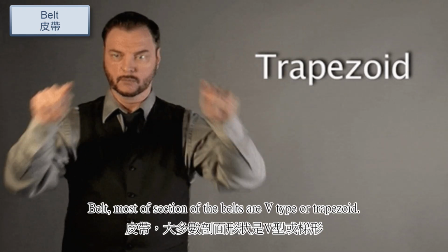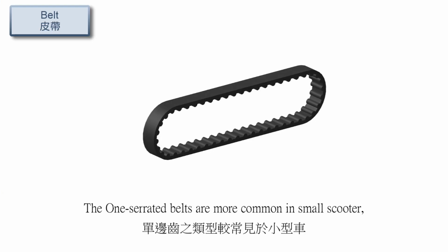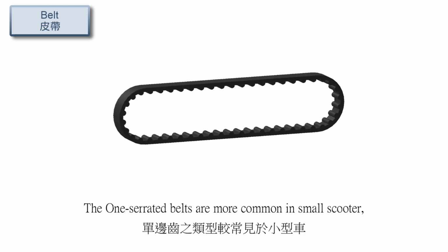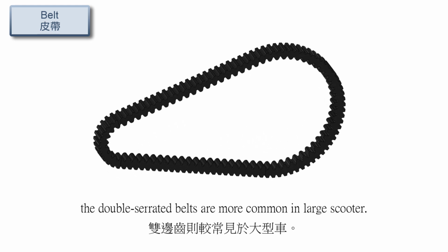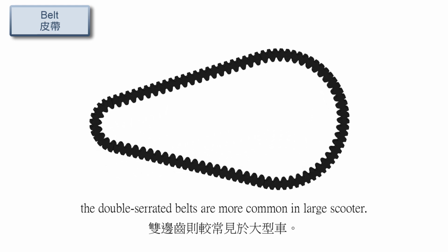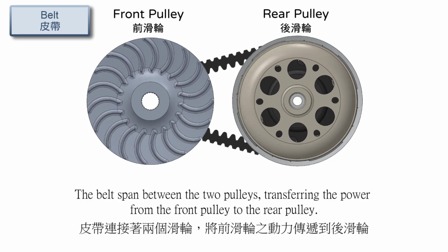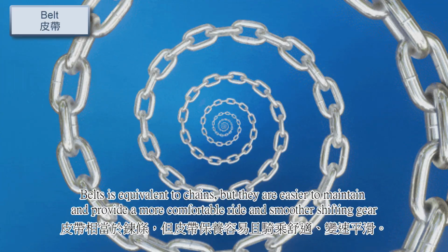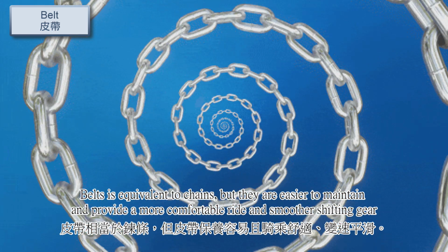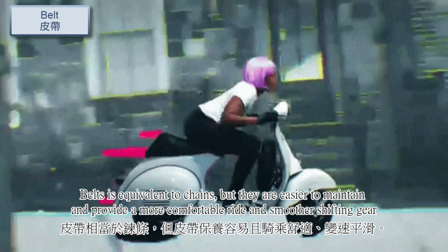Belt. Most belts have a V-type or trapezoid section. The single-serrated belts are more common in small scooters. The double-serrated belts are more common in large scooters. The belts span between the two pulleys, transferring the power from the front pulley to the rear pulley. Belts are equivalent to chains, but they are easier to maintain and provide a more comfortable ride and smoother shifting gear.